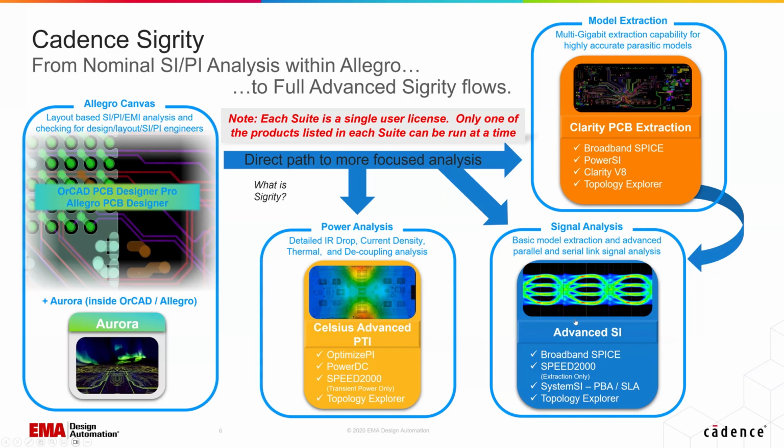For signal integrity, we have a main tool that allows both parallel bus and serial channel. For the signal integrity flow in the time domain, we have three options for extraction. Typically you want to get the board parasitics accurately represented in a model, and we have three options for that depending on your signal speeds. So that's kind of where I'm going. I'm going to focus on signal integrity for this particular board that Orlin was talking about.